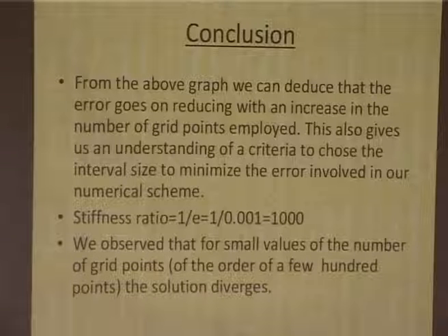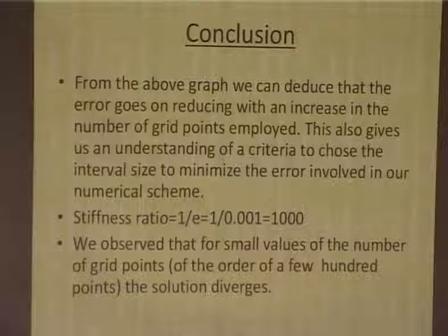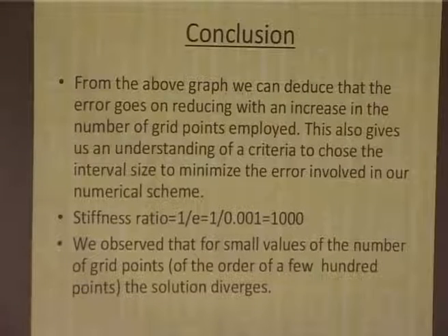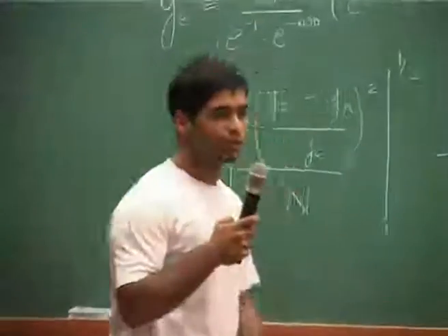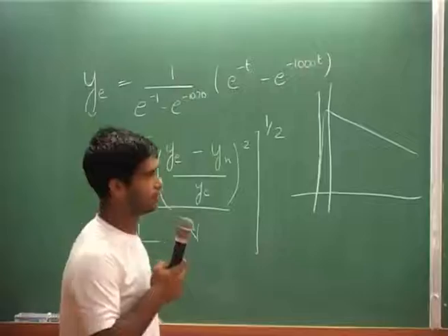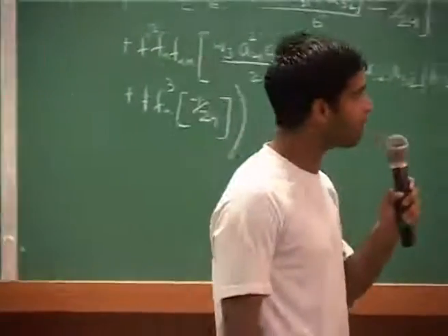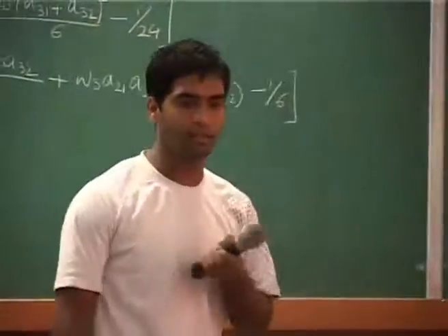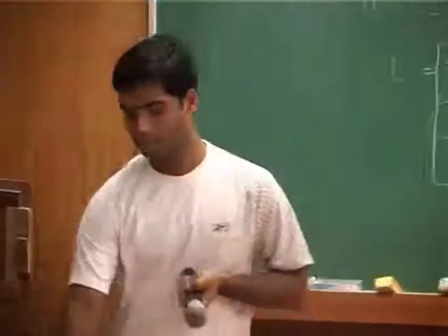One more important thing, we observe that our solution has two parts. As sir said, if we take the fast Fourier transformation, there will be two frequencies dominating, like he showed for the two modes. So the analytical solution explains that part also. We also took some smaller values of the grid for which the solution diverges very rapidly. So that also puts a limitation on the step size.